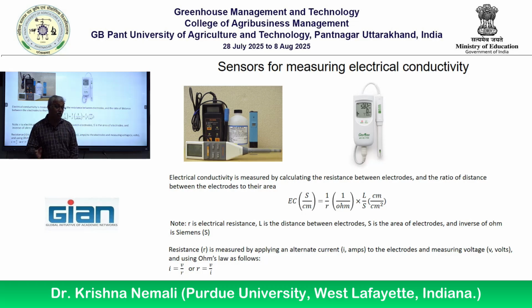By the way, in most of the greenhouses, hydroponic greenhouses, it's a continuous EC measurement, right? Inflow. Maybe when I talk about hydroponics, I will talk about that. We maintain an ABC tank system, 3 separate tanks. Each tank has a different fertilizer. As the fertilizer water is coming through, we measure EC instantaneously. If the EC is lower than what you want, automatically it is dosed, right? That is different. So in such situations, it may be very useful to calibrate more often.